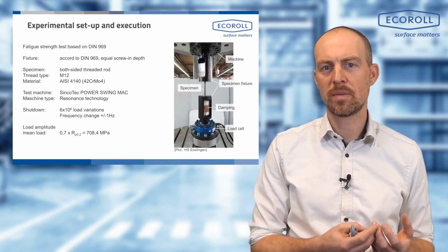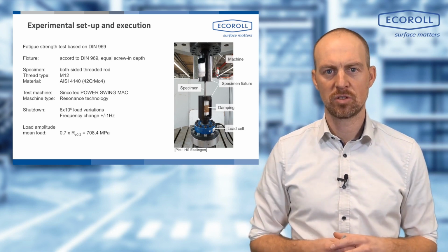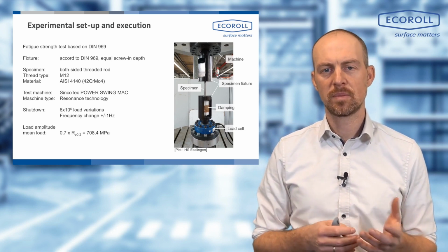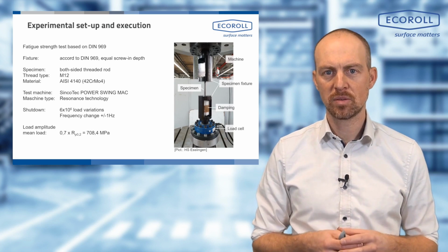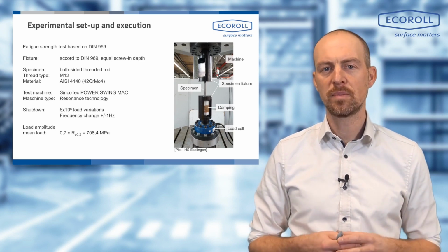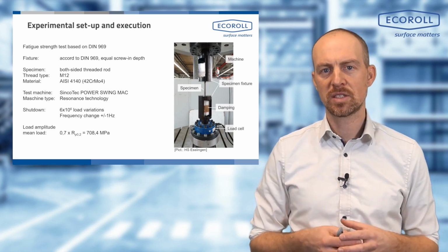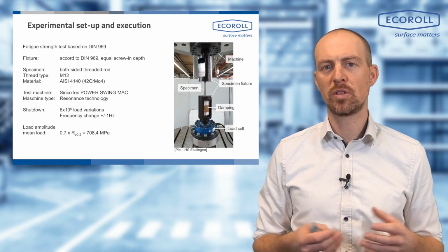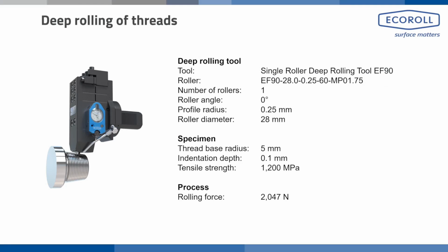reliable result here. We manufactured the threaded rods here, an M12 thread from a 42CrMo4, tested in a resonance testing machine and then recorded various Wöhler curves. I would like to explain the thread rolling process separately once more. In thread rolling, we used a single roll rolling tool.